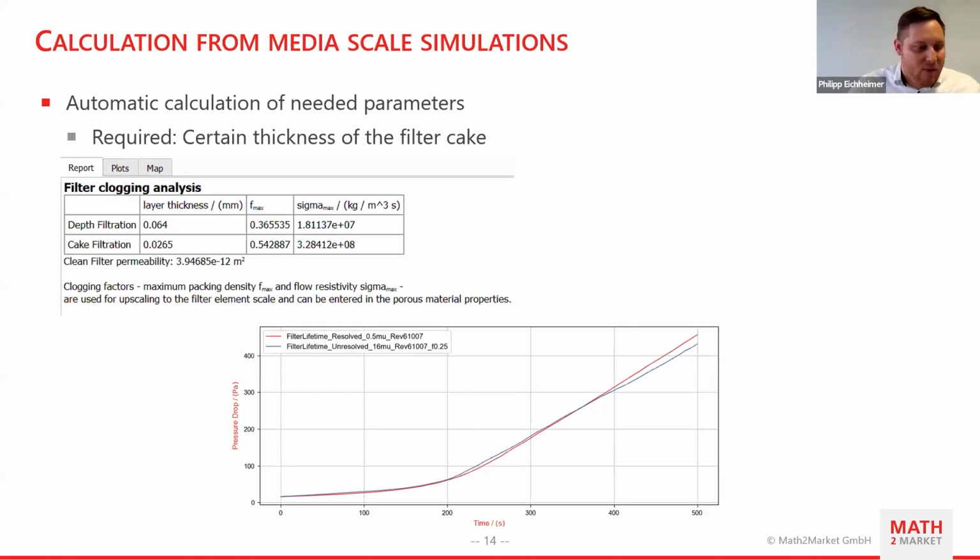But from the experience I have, for example, a filter lifetime simulation, when you have a filter media with reasonable sizes and good hardware, takes 1 or 2 days. When you go for a clean filter media, and only want the initial pressure drop or the initial filtration efficiency, this takes up to a couple of hours. So this is not an issue in that case.